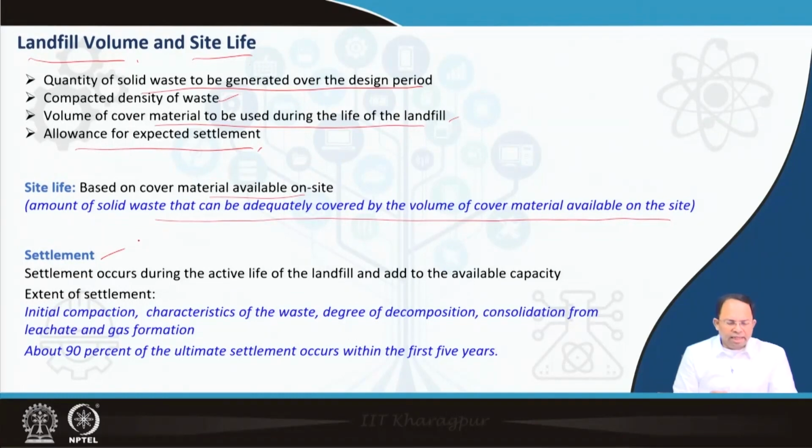Settlement occurs during the active life of the landfill, and also later on as well to a certain extent, but less. And it adds to the available capacity of the landfill. That means if the total volume is something, because of settlement we will have additional volume available, that needs to be considered. So the extent of settlement, how much settlement will occur, depends on initial compaction. If the initial compaction is low, then settlement would be higher.